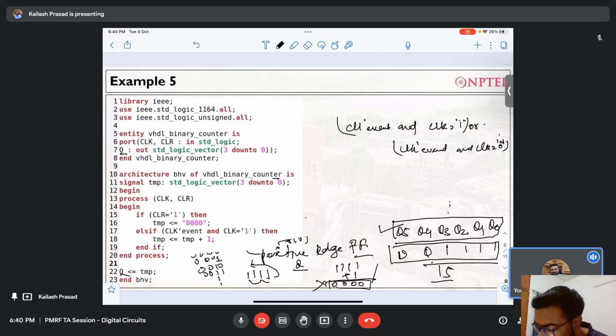You can write clock as posedge and reset as negedge, you can do that. But the same signal with both edges is not advisable in hardware description language. Whenever you synthesize the design, it will result in highly complex logic, which is generally not synthesizable.